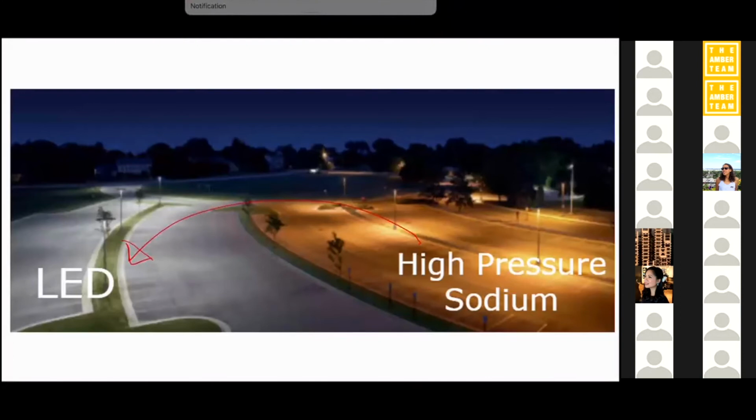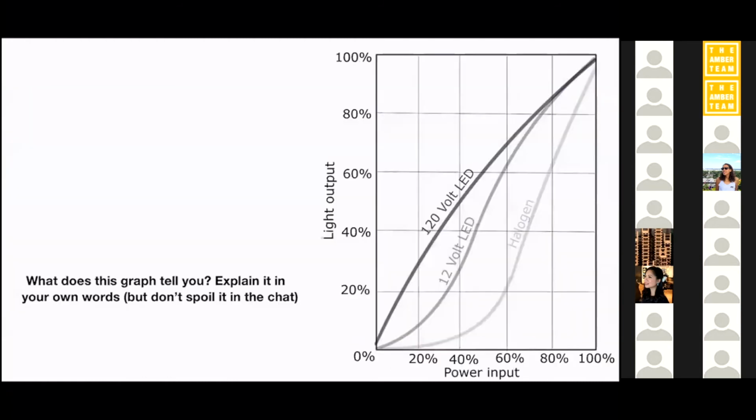And the reason we're doing it is not only because a lot of people prefer the look of the LEDs, and because your clothing and your skin look better under LED than they do under high pressure sodium, but we also do it because LEDs last a lot longer. And as you might imagine, it's pretty expensive to get a bucket truck out here and relamp these every 50,000 hours. We'd rather relamp them every, I don't know, 200,000 hours. That's a much better proposition. And LEDs used to not be any more efficient than these guys, but we keep making progress on LEDs to the point where some of them are now significantly more efficient than the other versions.